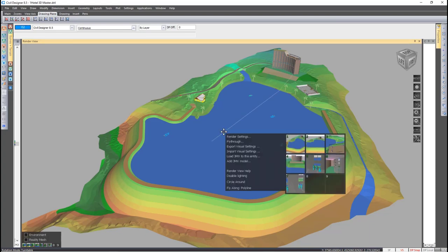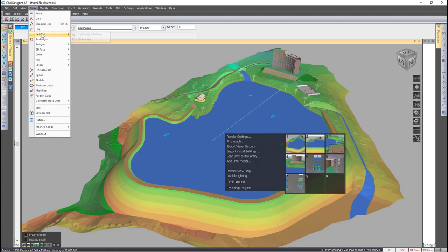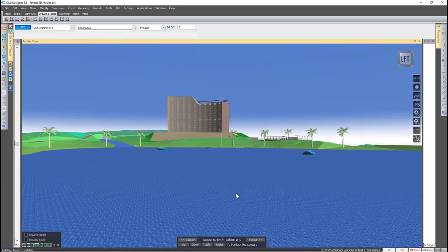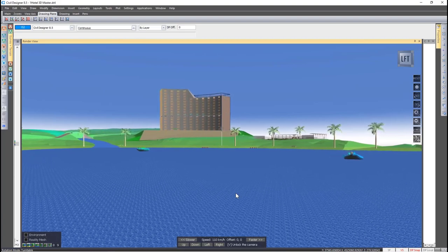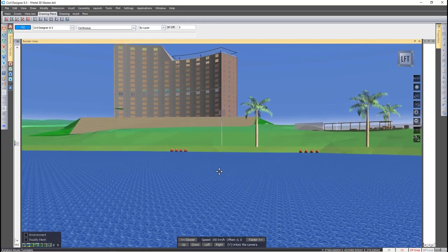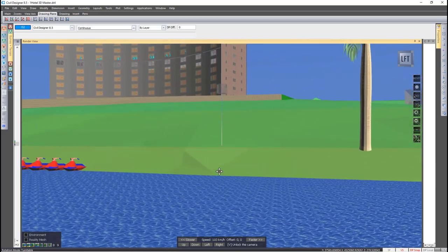With it turned on, if you go and right click on this, you'll see that I've gone and created a polyline. And there's a trajectory symbol showing you what the fly through would look like. If I go to draw inside the CAD Pro module, you'll see that you have the polyline as well as the spline options active. So giving that a go again, I'm then going to right click, fly along polyline. If you watched the first CAD Pro webinar, you'll know how to control the speed of this. Going towards the hotel, I've gone and created a superficial elevator there.